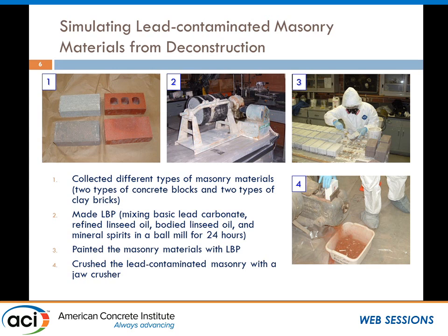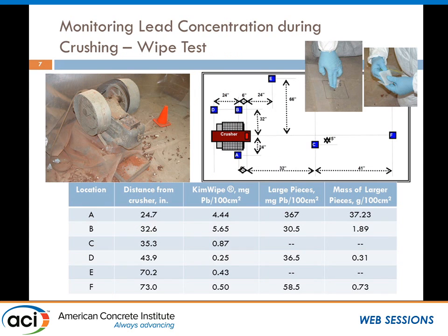The next stage is, of course, when you want to use it for concrete, you need to crush that. We use a jaw crusher with an opening of about 3/4 inch to crush all these bricks and get a proper size for concrete purposes. One major concern we have is, during this demolishment, what kind of contamination you're dealing with. It's not directly related to concrete, but we want to know exactly how much lead we are dealing with.